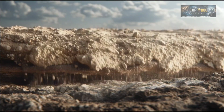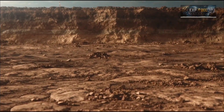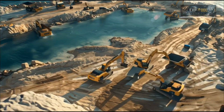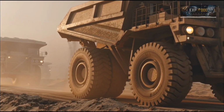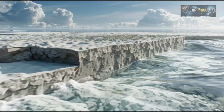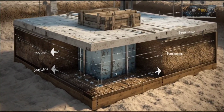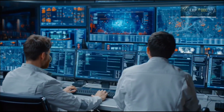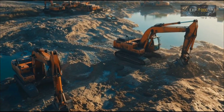After several months, or sometimes even years, the excess sand is removed, and only then does construction of permanent infrastructure begin. At the same time, engineers continuously monitor the condition of the island. Specialized sensors are installed across the entire site to detect even the slightest changes in ground elevation. In some cases, settlement is measured with an accuracy of just a few millimeters. If the measurements differ from the predicted values, construction plans are immediately adjusted.